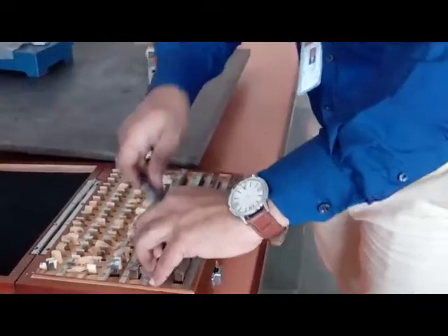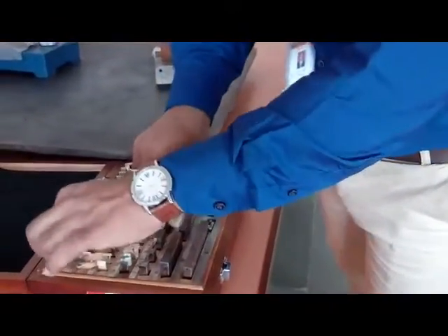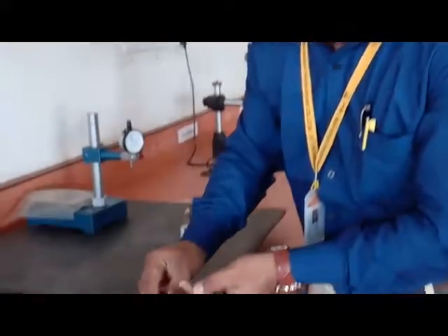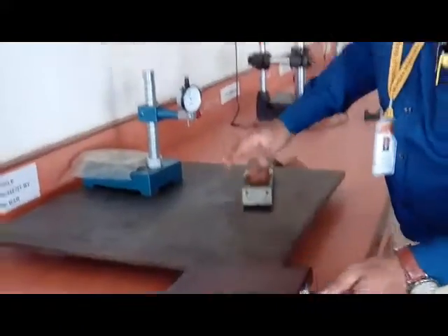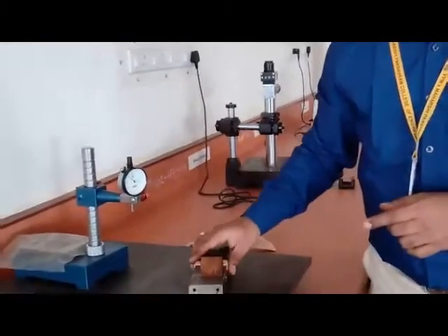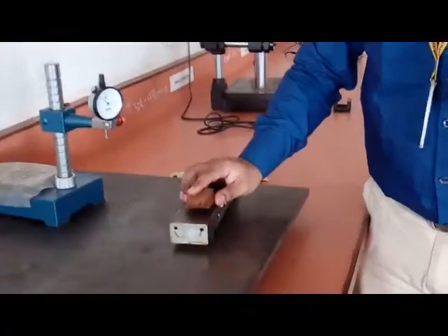Now, after performing the experiment, we have to take care that the slip gauges are greased again. They have to be greased up, and after that they will be kept into the box as per the dimensions. The wax paper is generally used in order to protect the slip gauges from any rust, any corrosion, or any foreign particles attacking them. So we will keep all the slip gauges as per their position, and after this, we will take out the sine bar. Again, we will grease the sine bar as per requirement so that dust particles won't affect your calculations.